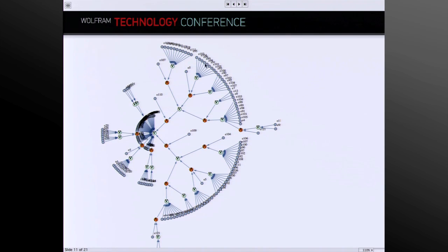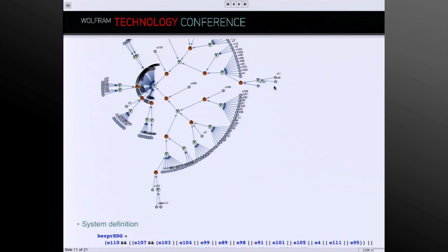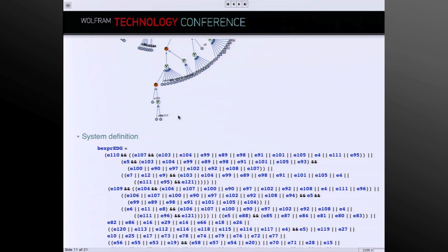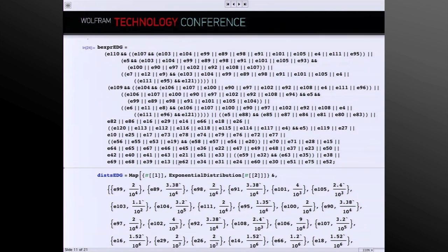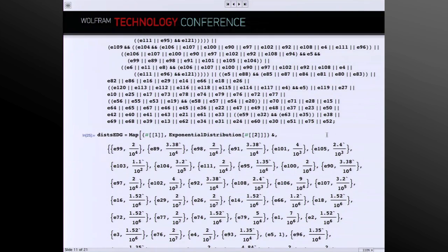And these events in turn trigger a bigger event. And when this thing here in the middle, when the central event happens, then you basically have one diesel generator down, and hopefully you have more than just this guy. So to input this, you'll enter the corresponding Boolean expression and the distributions to match with the Boolean expression.